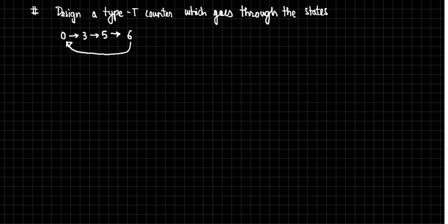No. Unless and otherwise specified, you may take it as don't care. Okay, we don't care if it goes to 1 or 2 or whatever the states, the remaining states which are not covered here. Okay, if it goes to 1, 2, let me write that, 1, 2, you tell me 4 and 7. Okay, if it goes to these states which are invalid, okay, we don't care. But if I specify that I want to reset the counter when the states are there, then you have to be careful. Okay, then there won't be don't care, there will be zeros involved there, or ones involved there, you don't know. Okay, you got what I'm saying?